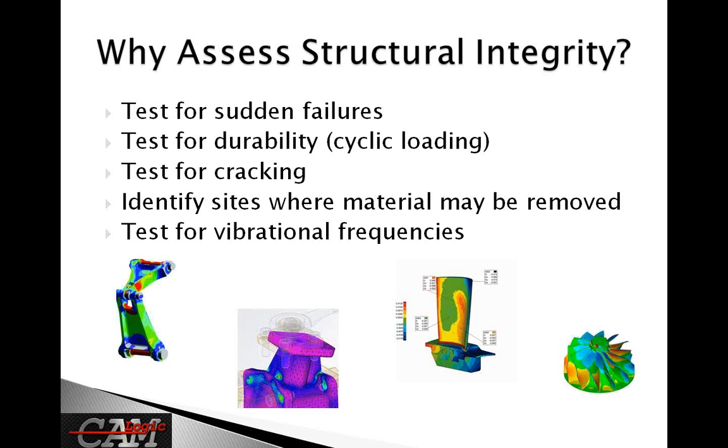And when there is a match in the frequencies, then you know that you will have excitation of the component that can lead to higher forces and will contribute to failure. And so an issue of structural integrity is to make sure that vibrational frequencies at the component level are not in the same range as frequencies in the system during operation. And there are ways to add material and remove material in order to adjust the frequencies.